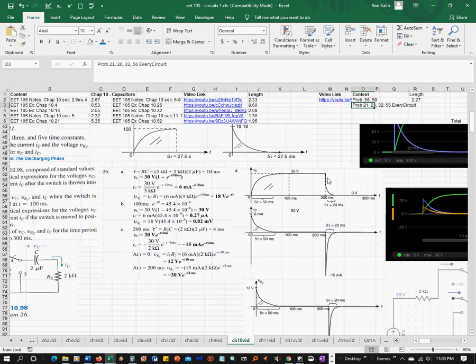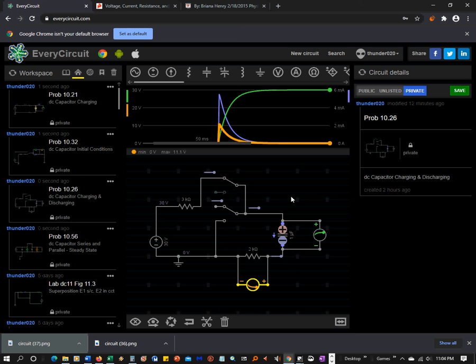This was V sub C in this phase, and then I sub C in the initial phase, and then V sub R2 in the initial phase. So you could see that they're basically the same thing. So the next step is I'm going to put it into position 2. So I'm going to keep going. This is position 2 right here. It does nothing. It doesn't change anything. And then when I flip this switch, I'm going to go into position 3 and it'll be discharging.